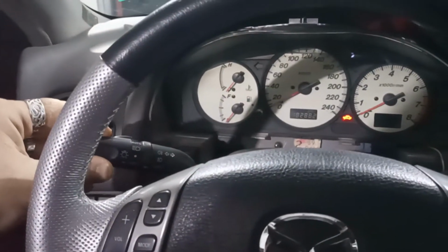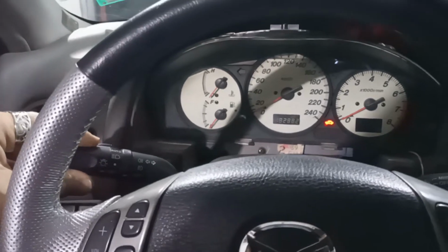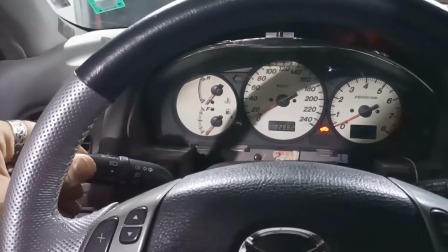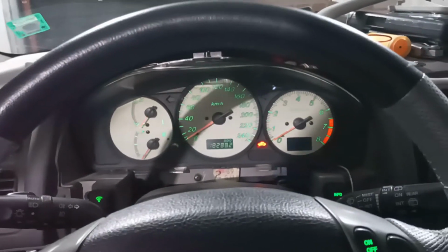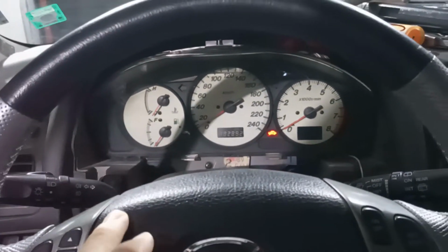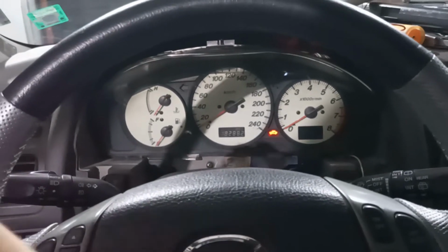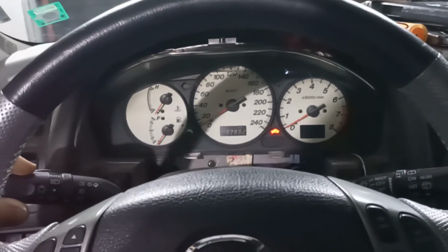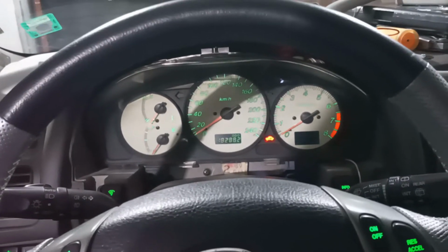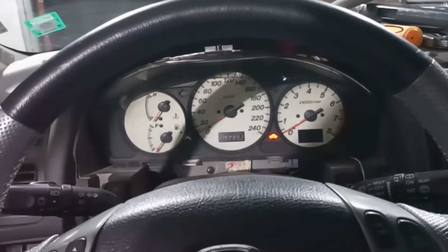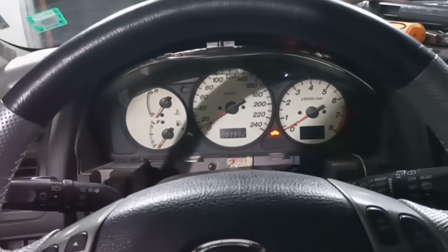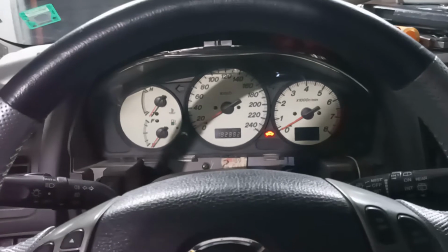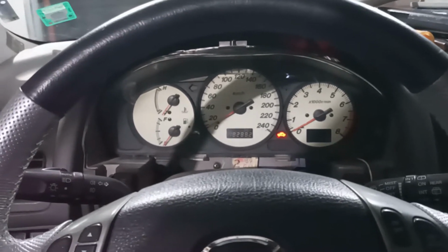So let's go back to 4. Instead of tapping back, I'm going to reverse from increment to decrement. So hold it a little bit and then go back to off, and now it says short, then long. That means now we are going down. Down from 1, there's no 0, we go back to 4. 1 short beep. Short means more than the default, and it's 1 more than default. Default is 3, 3 plus 1 equals 4. So the value of parameter 7 is now 4.